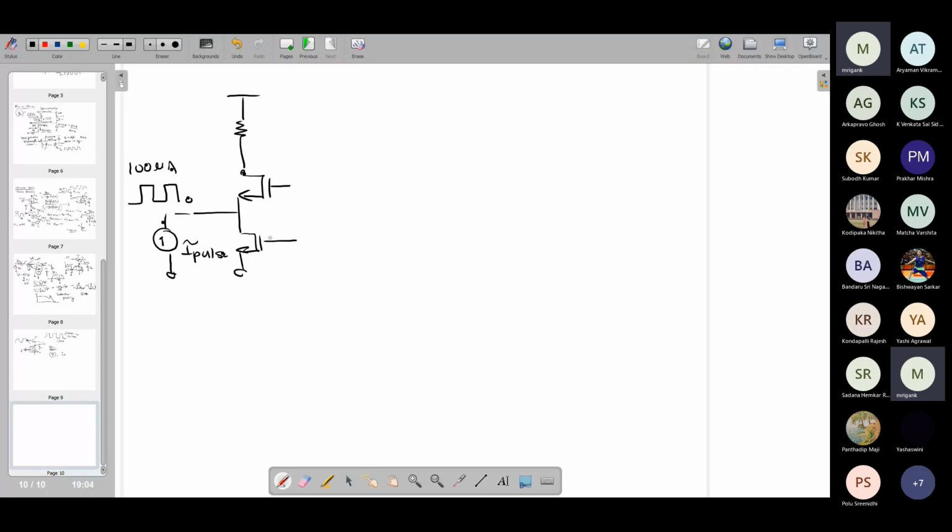And here you are supposed to get the bias current of this one. It has to be some appropriate value. You need to think about how to set the I bias that we have already discussed in the class, but right now, based on the discussion, you can figure out the value of RD. And of course, here you will have the right kind of biasing circuitry. You can use, for the time being, RG1, RG2. And this one will be a current mirror. So you can use a current mirror. Here you will have a reference current, so whatever current you want to put, IREF.